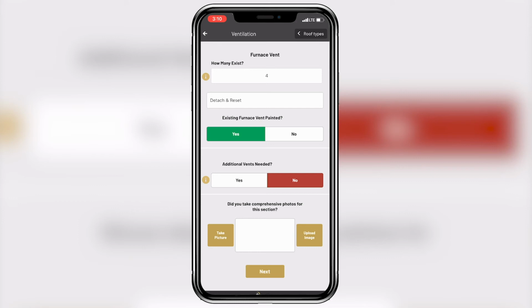One thing to keep in mind when thinking about this is that if the home has any vaulted ceilings, that doesn't contribute towards ventilated attic space. So we can't account for that area of the home wherever there's a vaulted ceiling towards the ventilating space. In that scenario, make sure to double check that so that way we can get everything accurately accounted for.